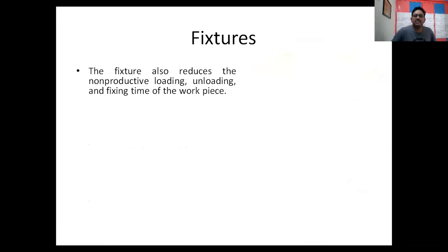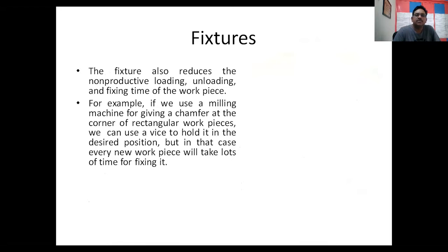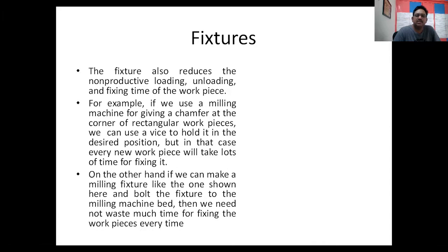So the fixture also reduces the non-productive loading, unloading and fixing time of the workpiece. For example, if we have a milling machine for cutting a chamfer at the corner of a rectangular workpiece, we can use a vise to hold it in the desired position. But in the case of every new workpiece, it will take lots of time for fixing.